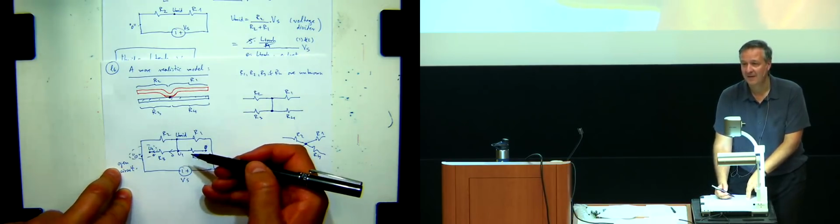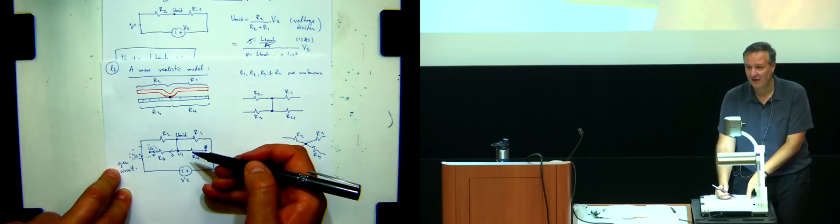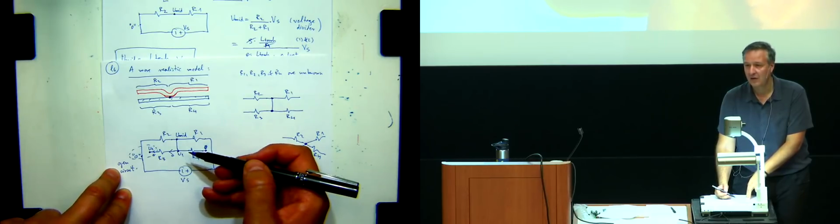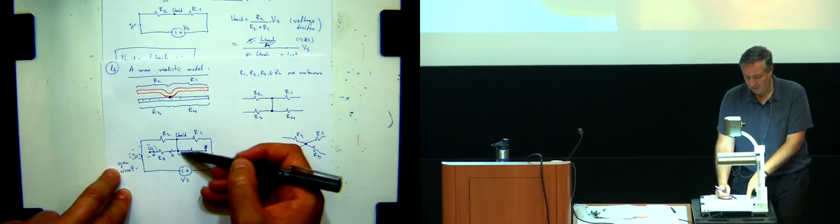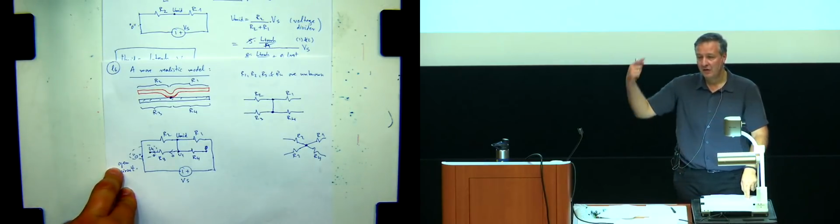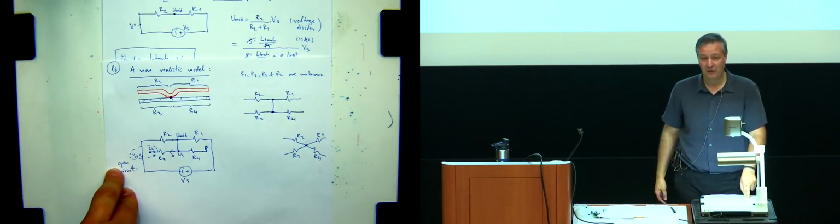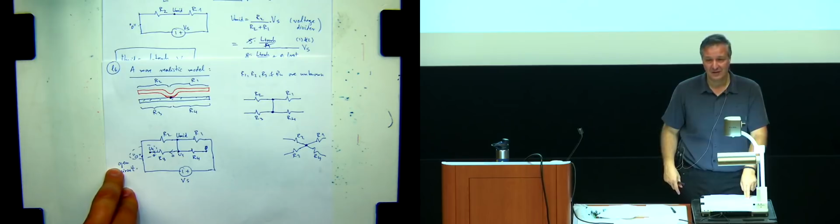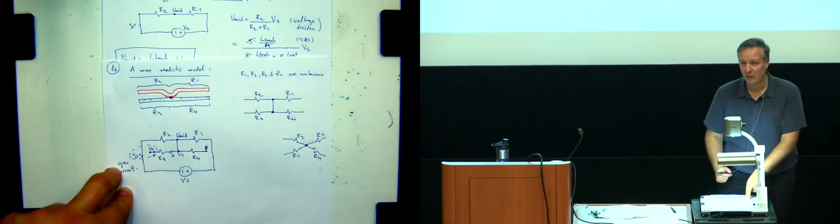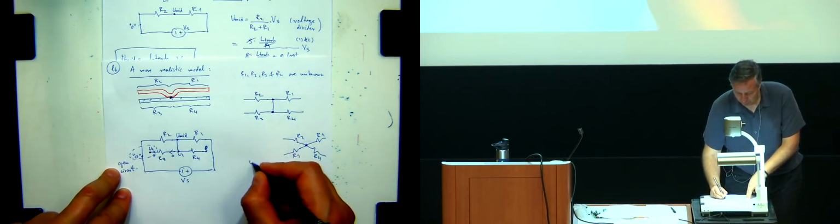Since it's only a wire between U1 and U mid, then, by definition of a wire, the potentials on two sides of the wire are equal, which means voltage across it is 0, and therefore U1 equals U mid, right?